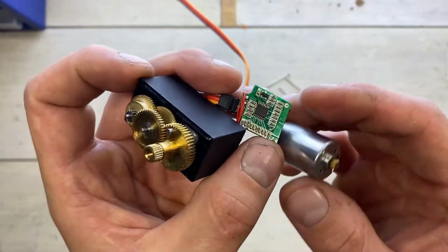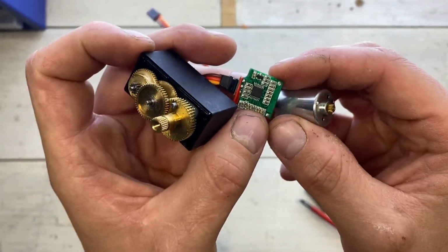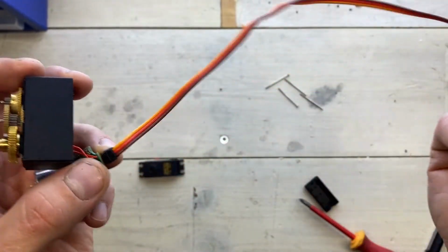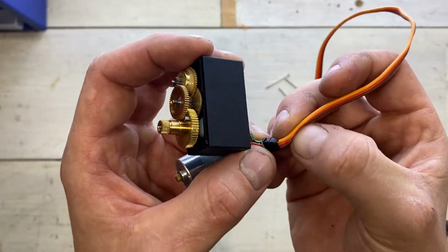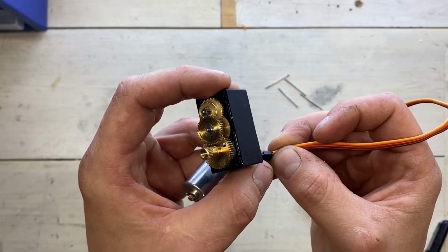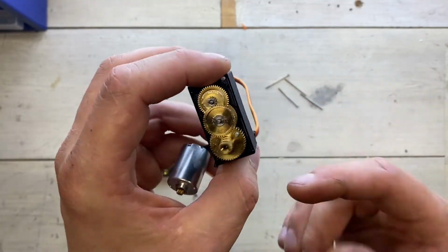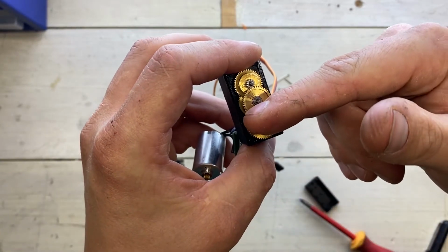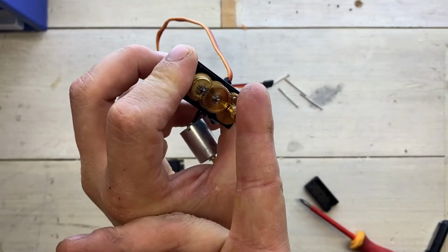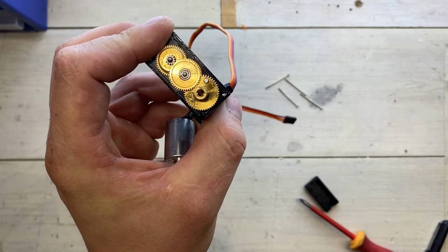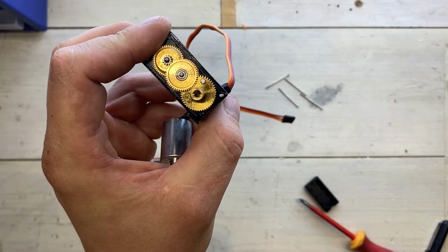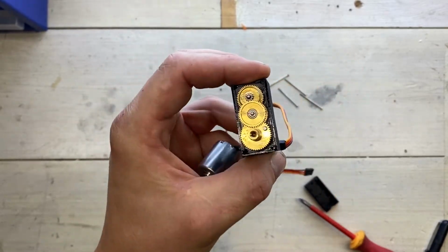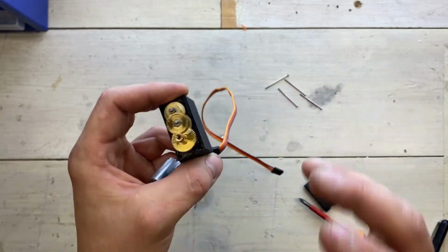And this little circuit is actually the servo driver. It is designed to accept a PWM signal, or pulse width modulated signal. And this pulse width modulated signal tells the servo how many angles to move between 0 and 180 degrees. And these are probably the smallest, cheapest servo systems there is. And they're also relatively precise and can be quite useful.